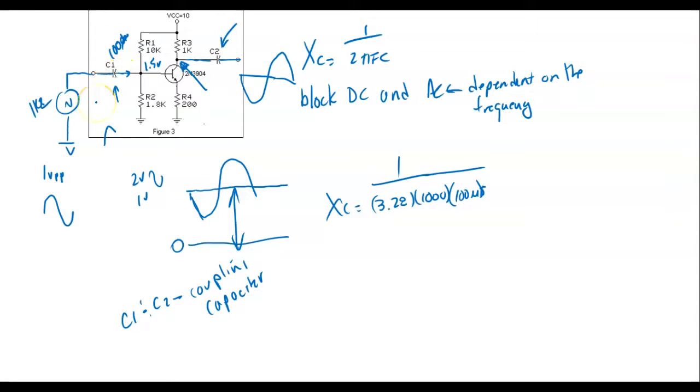If I left that coupling capacitor out right here, this bias voltage would drop down to about 0 volts, because the DC sees an AC source as a short circuit, and an AC signal sees a DC source as a short circuit. So that's why, when the signal flow comes in, what does it do? It comes up here and splits, because the DC signal sees that as a common. It doesn't see that DC power supply, and it goes this way and that way. And that's what your AC signal sees.